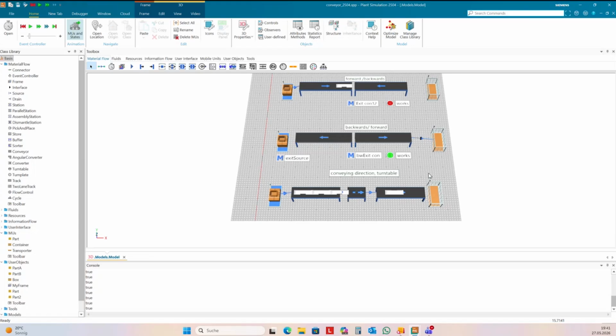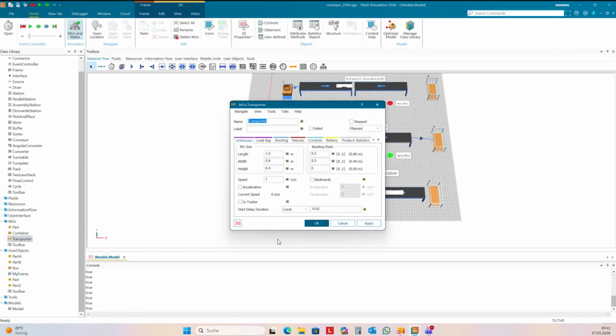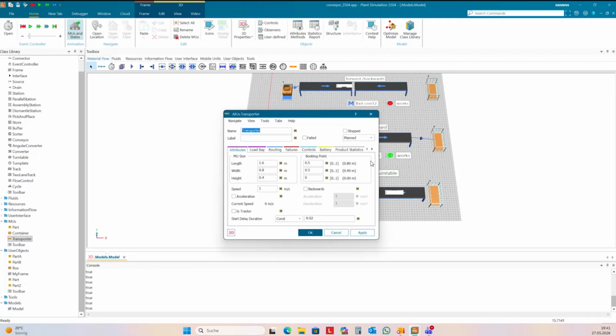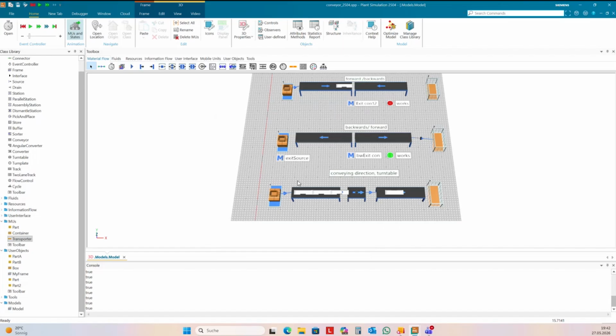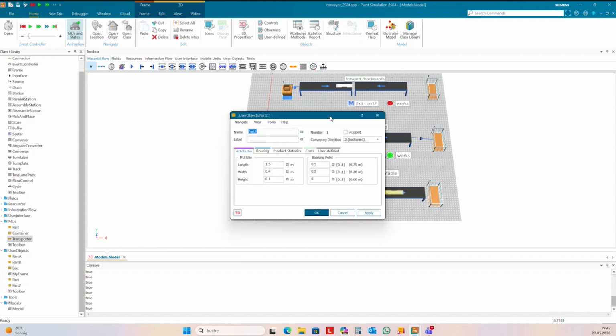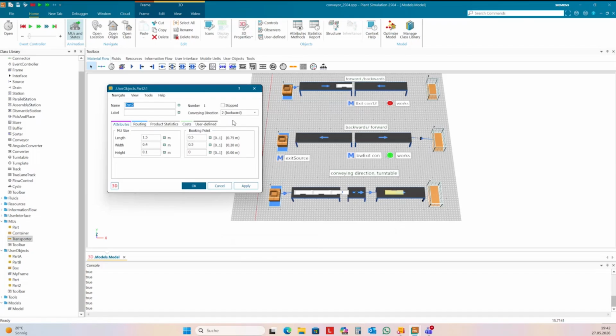And in the meantime, Plant Simulation or Siemens don't succeed to change the conveying direction by yourself. And so you have, I guess, the conveying direction of the transporter. It's not here anymore. Here in the main dialog of the transporter, it's missing. You cannot change this directly. The transporter has itself conveying direction as an attribute, but you cannot change it. You can change it with SimTalk, yes. And so it's here in the conveyor system. It's safer and more stable if you change the conveying direction using the elements Plant Simulation supports. Okay.